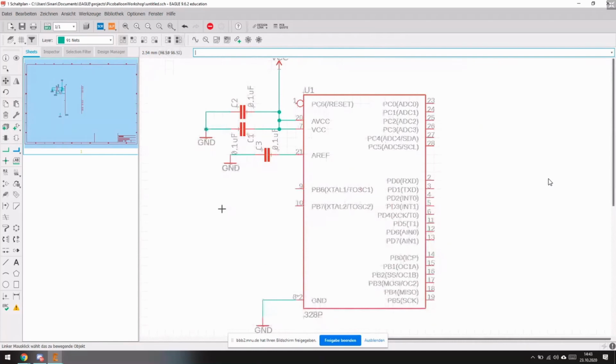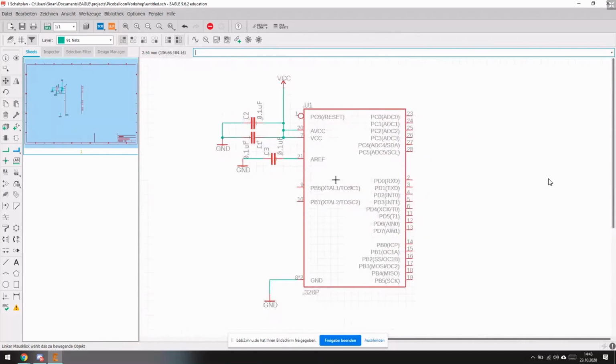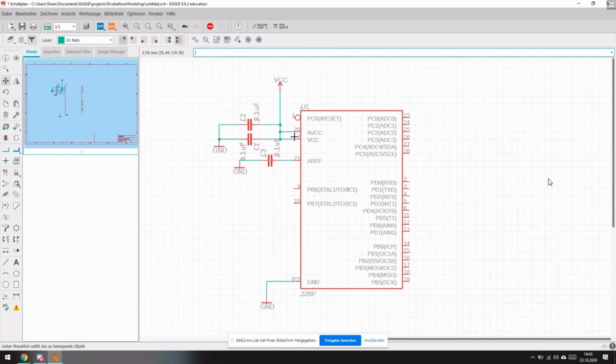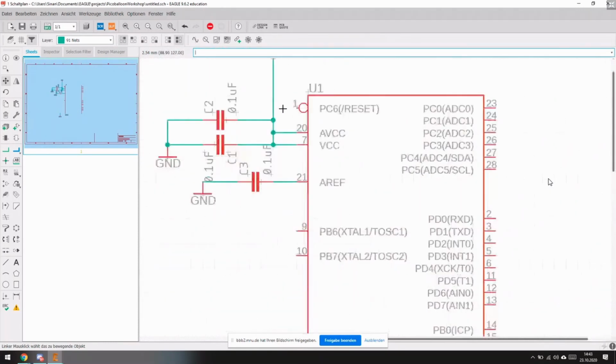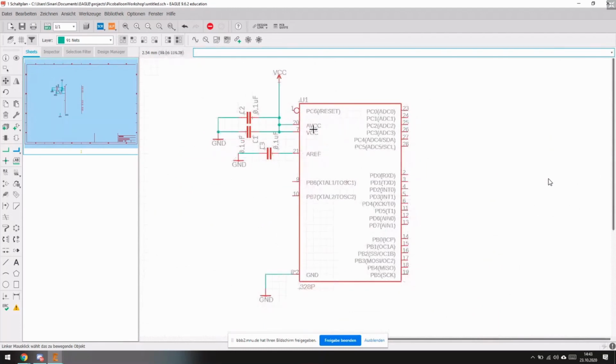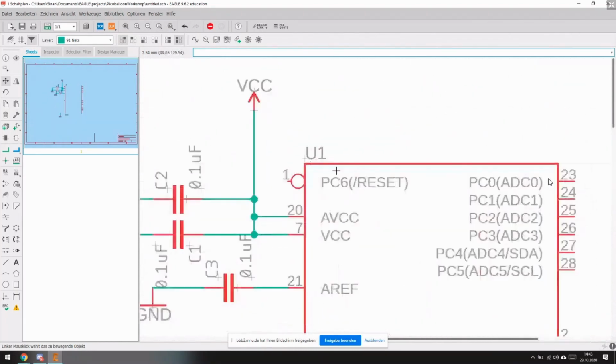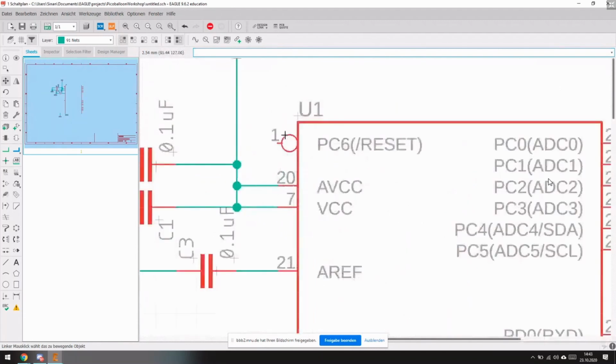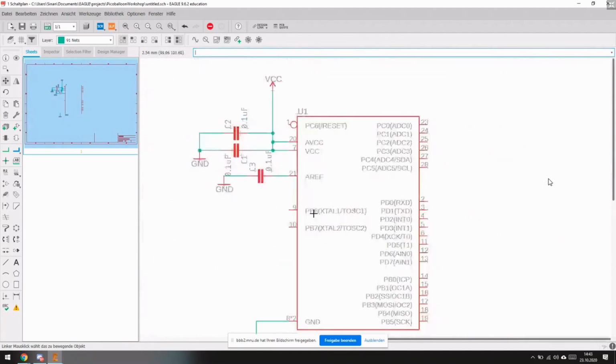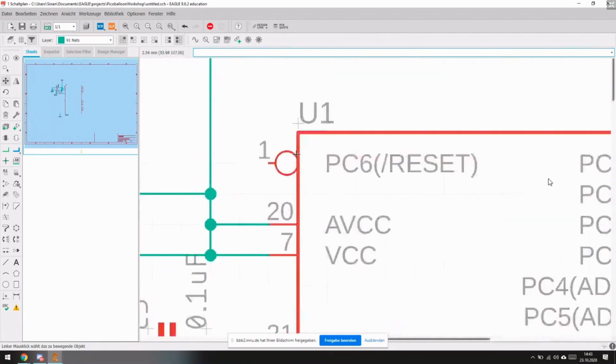So we just powered our microprocessor up. This is the minimal circuit we have to do, because it's just supplying. Well, if the chip is programmed, this would be the minimal circuit. But of course, we want to program it and do stuff with it. So we will just connect the reset pin here. As you can see, all the pins are normal except for the reset pin.